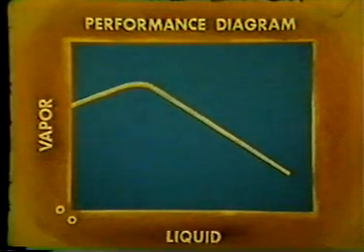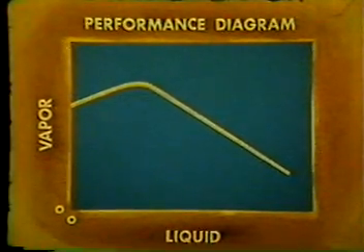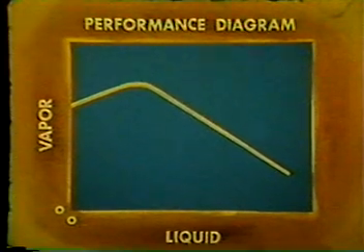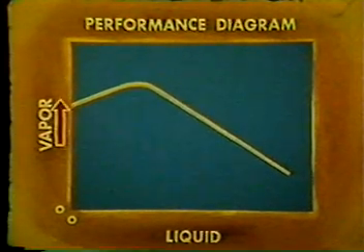The behavior of the vapor-liquid mixture on the tray covers a wide range of flow regimes from bubbly to spray conditions, depending on the systems and operating conditions. This is a typical operating diagram. The horizontal axis represents the liquid rate, and the vertical axis represents the vapor rate.